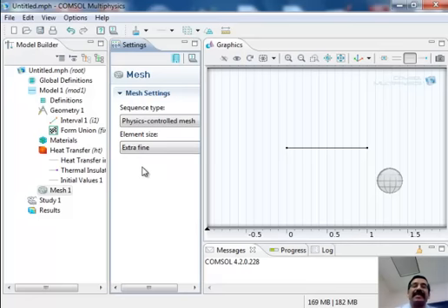So once I do select that, I say go and build the mesh. So it has built the mesh for me. And how do I know it has built the mesh? It gives me the information here. Mesh consists of 50 elements. So it has divided the domain into 50 elements. If you select extremely fine, maybe it will divide it into 100 elements, for example. But this is equivalent in our Matlab code to determine what h is, 1 over n plus 1. So that's what we have done so far. Any questions?